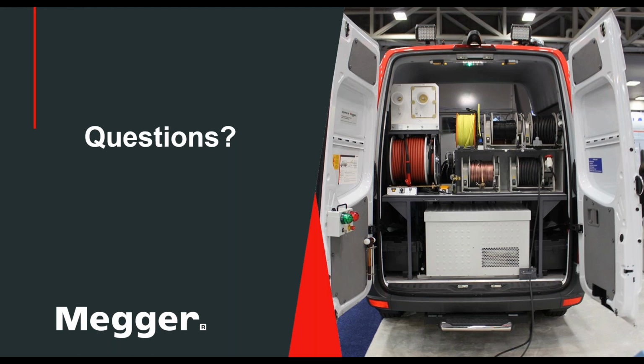It's not that the radar works sometimes and doesn't work sometimes. The radar, like any other tool, has certain limitations of what it can do and what it cannot do. So I cannot really give you an answer on how you would get an incorrect radar reading, because it depends how you get to that point. Typically the radar is probably today, aside from the thumper that provides the high voltage, the most important tool in fault locating of medium voltage power cables. And it's a very, very proven tool to do so.